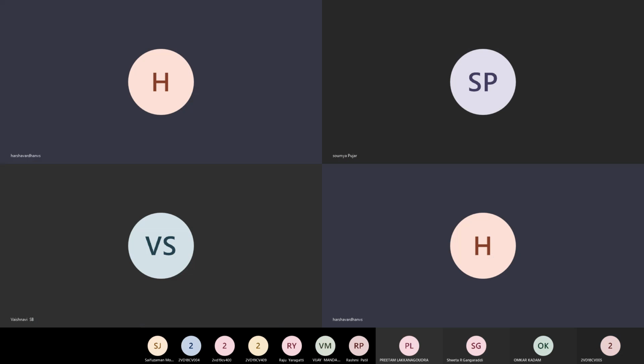So in quicksand condition, the soil loses all its shear strength and it starts moving in the direction of the flow, and that is what happens in the piping failure.